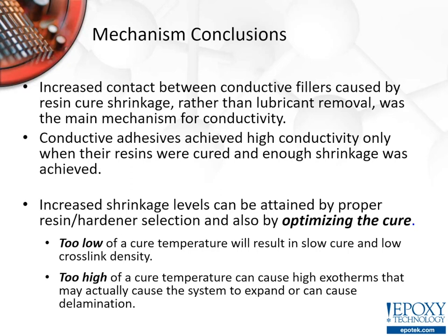Epoxy Technology has looked at ways of optimizing that overall connection or overlap by optimizing our shrinkage and the exact materials in terms of the silver packages that are put into the material. Through all these optimizations, we have found that not only are the proper resin and hardener systems required, but the optimal cure is required. Cure has a dramatic impact on electrical and thermal conductivity.